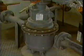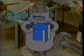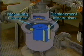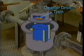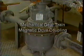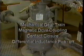Inside the housing is the precision measuring unit, made up of the measuring chamber and the displacement mechanism. The counter-drive train transmits the internal motion of the measuring unit into a usable output signal. This train may be a mechanical gear train, a magnetic drive coupling, a contact closure, differential inductance pickoff, or a combination of the above.